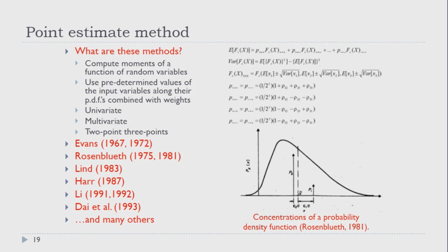So for example, we have cohesion as one input parameter. If your cohesion has a mean value of 10 and a certain standard deviation, let's say 5, so that gives a 50% coefficient of variation, we're going to calculate the factor of safety for 10 minus 5, which is 5, and 10 plus 5, which is 15.